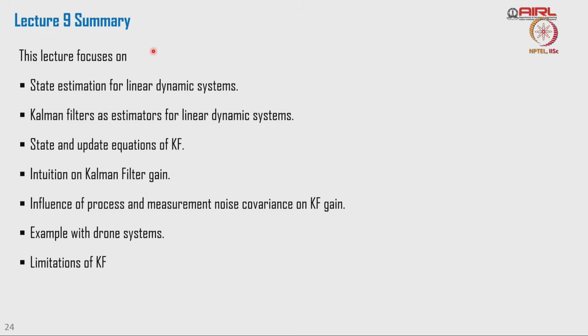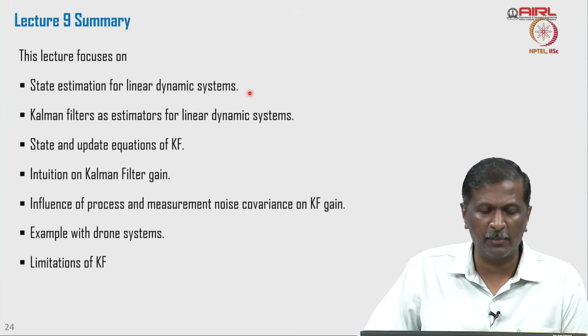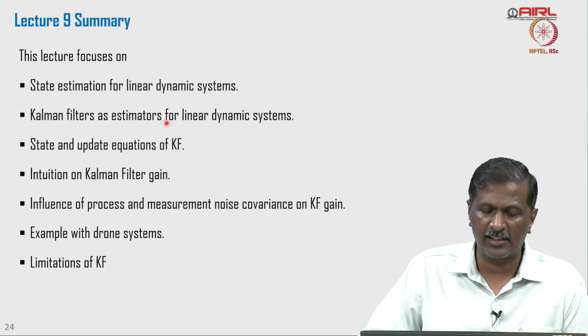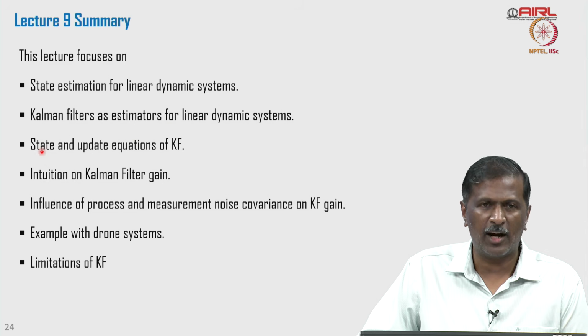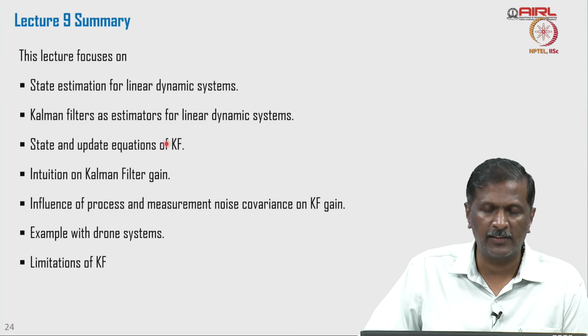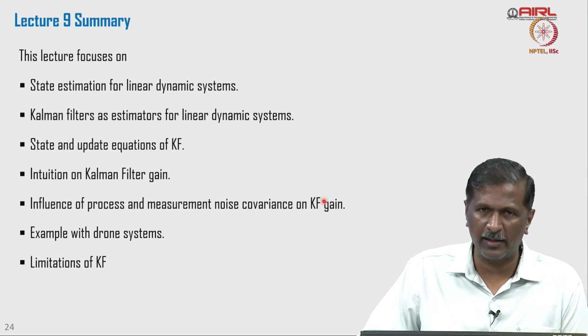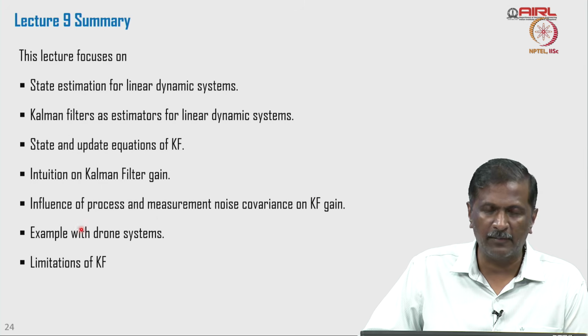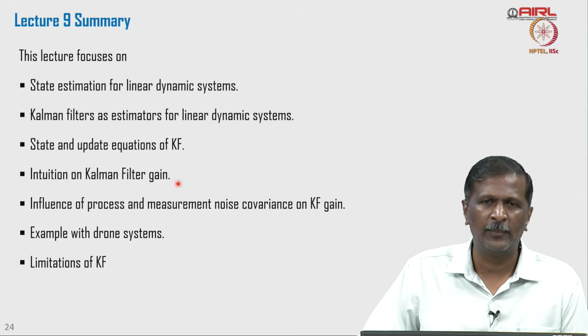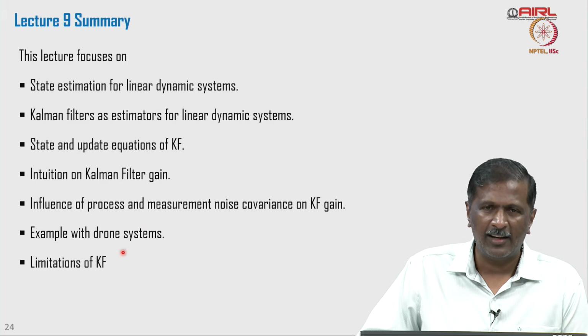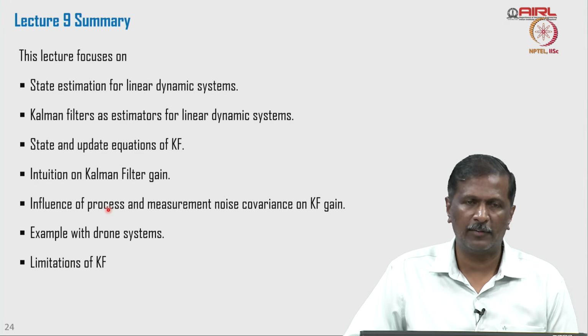So, I would like to summarize this particular lecture. The lecture focused on state estimation for linear dynamic systems. We talked about the Kalman filter as an estimator for linear dynamical systems, the state and update equations for Kalman filters, and the intuition of the Kalman filter gain, what its effect is, right. We looked at the influence of process and measurement noise covariance on Kalman gain, and we looked at the example with a multi-rotor system, the drone system, estimating the altitude, yaw rate and position, and we discussed the limitation of the Kalman filter.